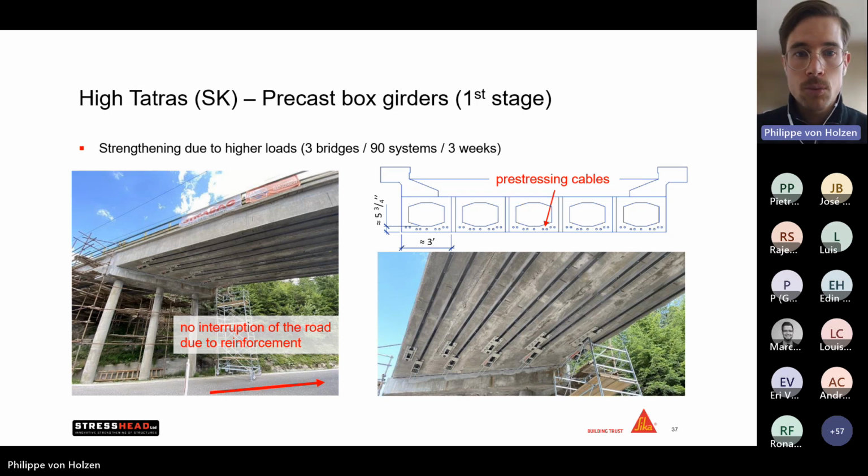The one I already showed with those much smaller shear pins to introduce the force, and a second anchor which consisted of 14 chemical bolts which transmit the post-tensioning force over those bolts without us damaging one of those existing span cables in the box girder.